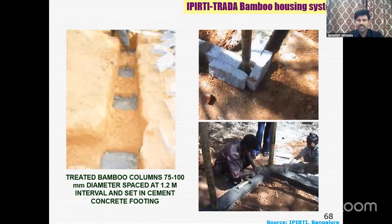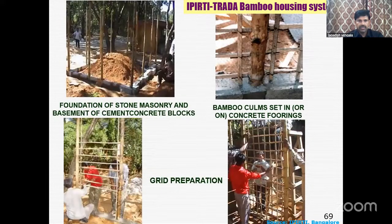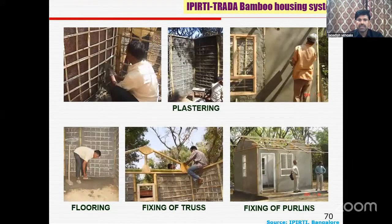These columns are connected to the wooden top plate. Between columns, you place a 6-inch by 6-inch bamboo strip grid. The strips are connected with steel bolts, then chicken mesh is tied, and then plastered.